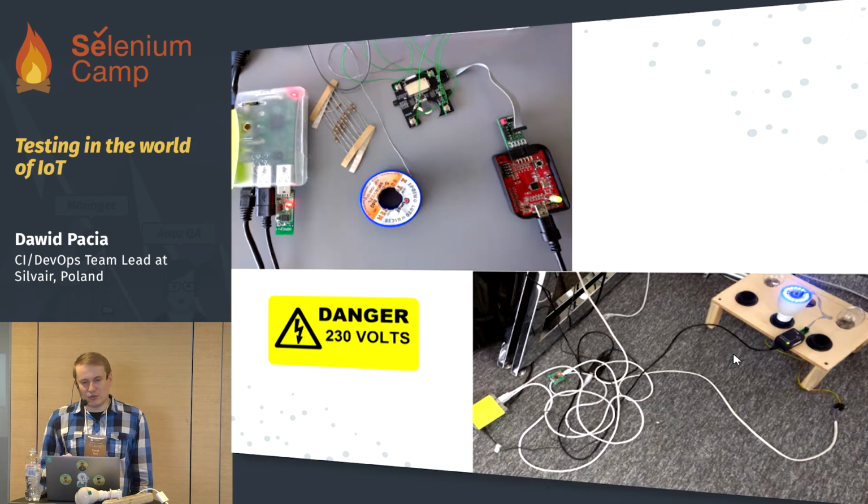And here is one very important lesson, because some hardware is working under high voltage, like 230 volts. And if you connect it directly from the embedded platform to the device, there is a really high probability that it will burn. Of course, everyone likes flames and fire, but it can cost a lot, and the most spectacular, I suppose, was to burn the notebook, the device and the debugger at once. And it was done by a student, but anyway, we got some lesson.